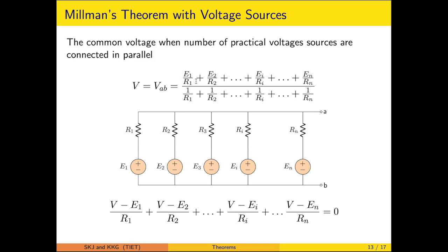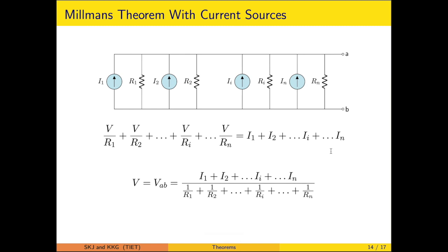So here I1, I2, I3 etc. We can keep on expanding the terms of the numerator. The denominator will remain the same. If the voltage source and a series resistance are represented by an equivalent current source and a parallel resistance, the formulation will be like this. When you correlate the two equations, the Ei appearing in the numerator is exactly equal to Ei upon Ri.